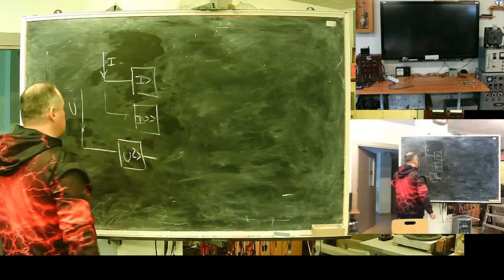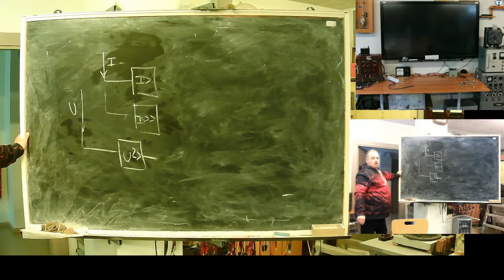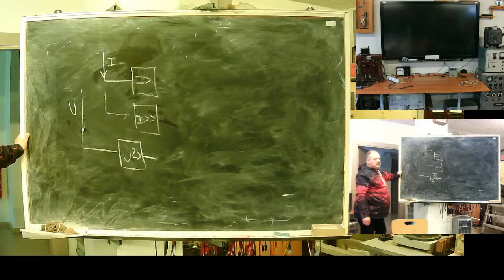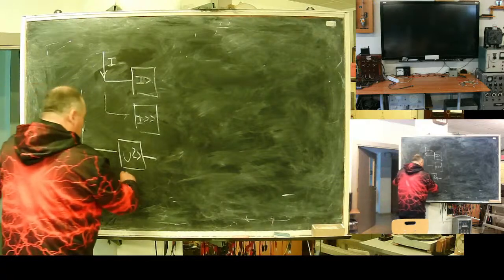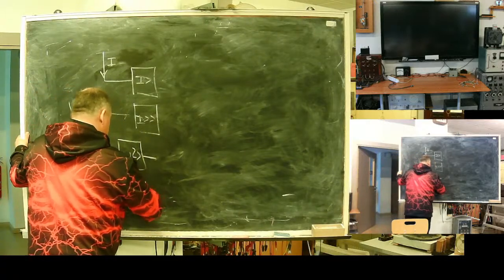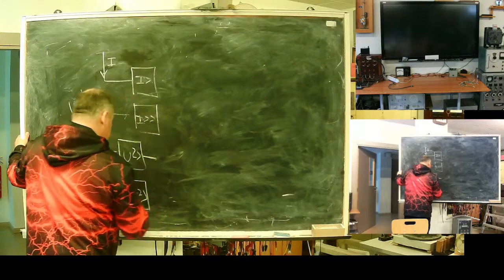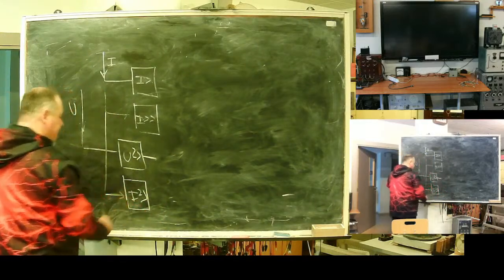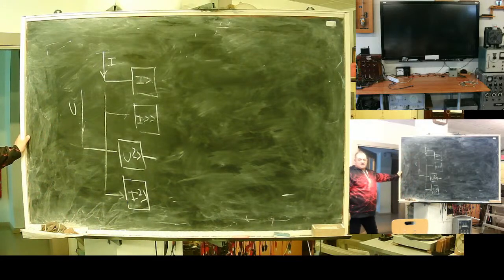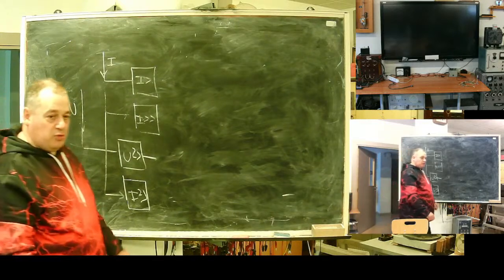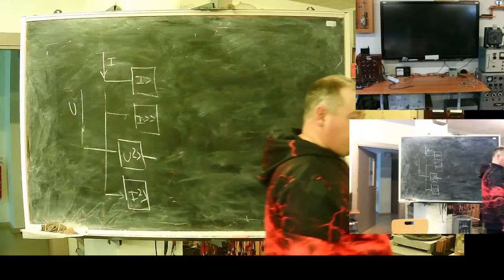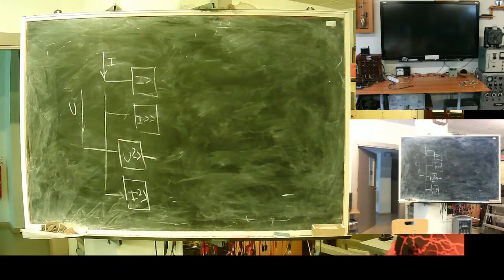In all directions, a negative sequence voltage relay is used. It's done by voltage because old negative current relays are unreliable. For modern ones, you can have a negative sequence current relay. Do you know what negative sequence is? What's your knowledge in symmetrical components? Fortescue transformation and things like this.